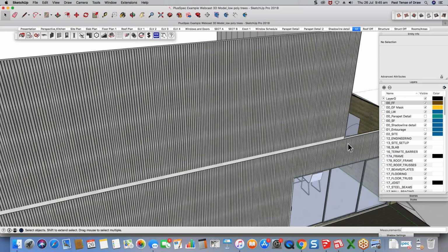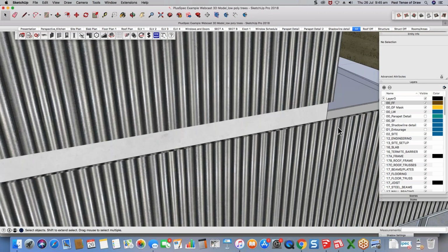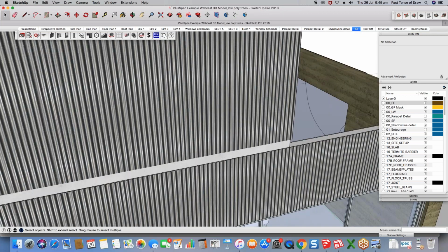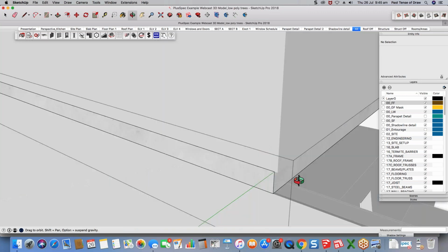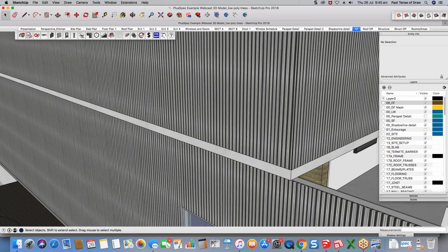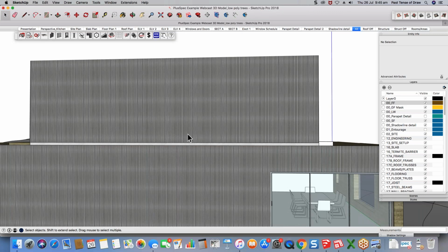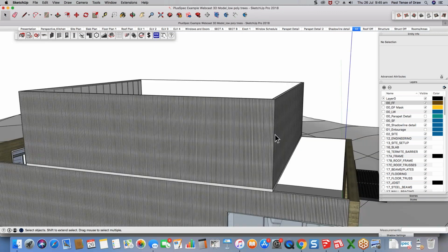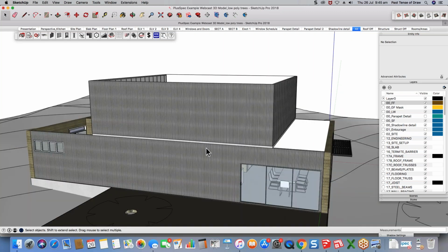So in this particular case, I could have even extended my slab out. So maybe I wanted to have an exposed slab there, and I could even just edit that now and say, well, yeah, I wanted my slab to be on the complete outside edge. And so when we're looking at this, we've got the exposed concrete slab there for an aesthetic reason, or to bring in some kind of horizontality or whatever. So you're really detailing and making those decisions as you go. Super intelligent, and again, based around structure, you cannot go wrong. I hope that explains it.